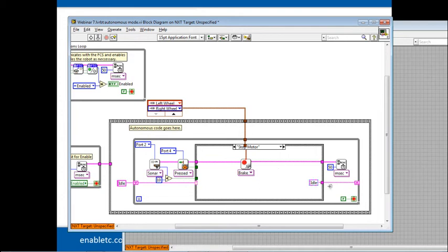By having a delay there, you can control the responsivity. The other thing is overall our loops respond better when there's a short delay. That makes sure that everything has time to function. And the third reason is, and this is a subtlety that I don't want to cause too much complexity for people, but there is a watchdog timer that's running behind the scenes in LabVIEW here to make sure that our Tetrix robots perform properly if the code were to fail. And by putting a delay in there, that makes sure that that watchdog timer gets hit.